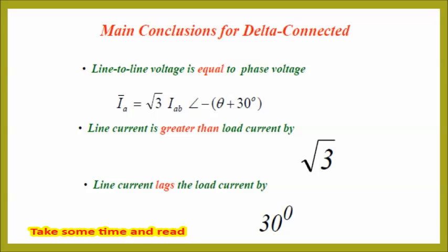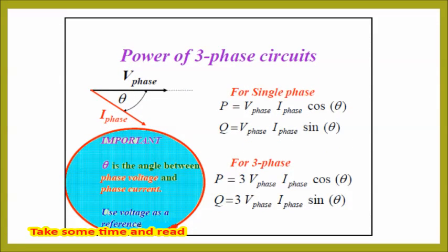As we know, in most cases, the single-phase voltage is 230 volts and the summation of three-phase voltages would be 400 volts. How does this happen? For example, as we now learned, in star configuration, the phase voltage can be taken if the line voltage is divided by square root 3. So in other words, if we multiply our single-phase voltage by square root 3, we can take the line voltage. In a 230 V single-phase system, it is as follows: 230 times square root 3 equals 400 volts.